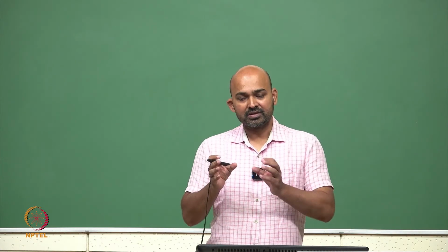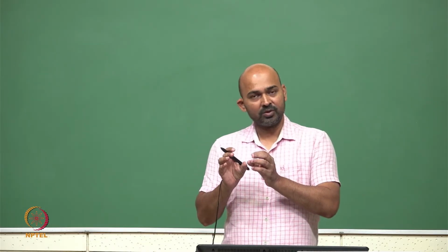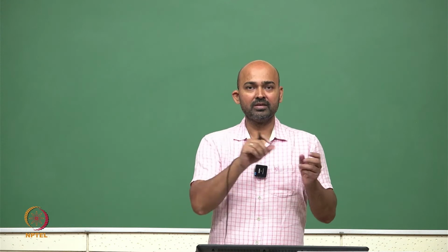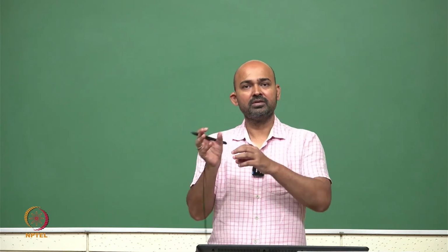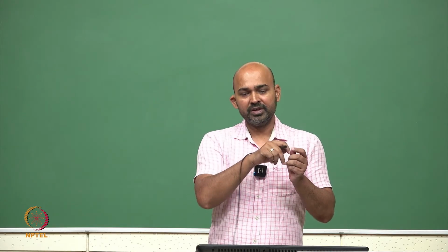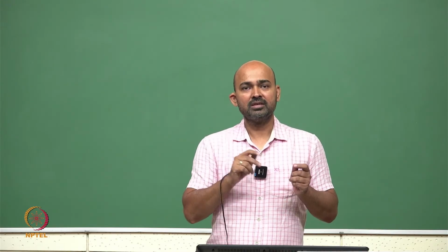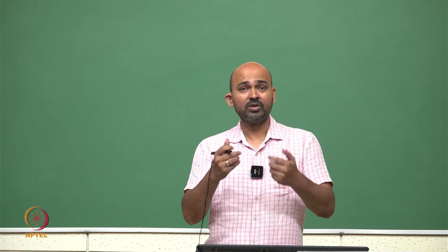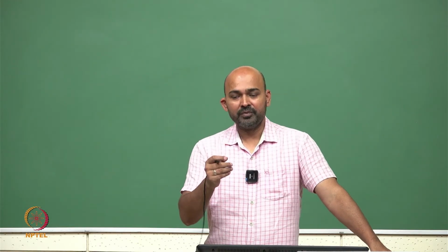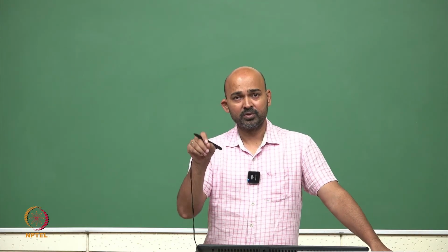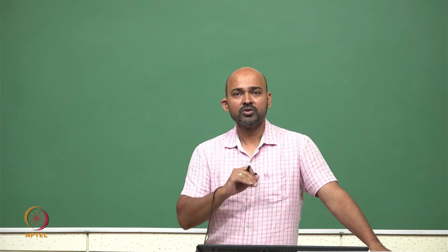There is also a very good option: if we have a large circuit and we want to connect so many components to each other, then because if we run so many wires, the schematic visually looks very difficult to solve. However, if we give the same name to that node, to that wire, they are assumed connected.